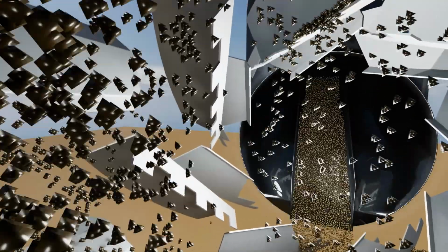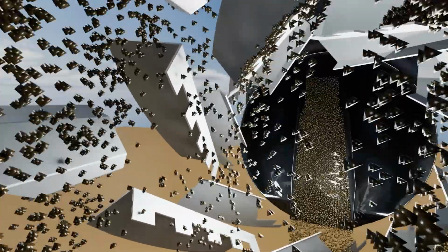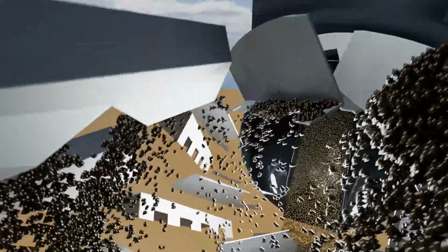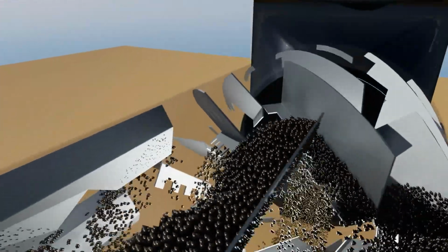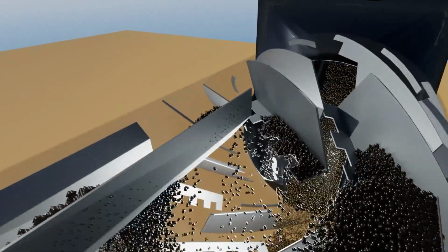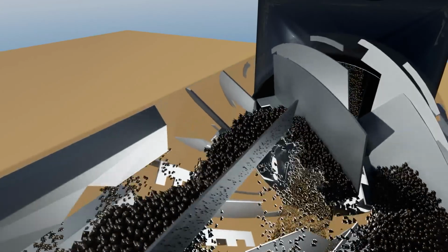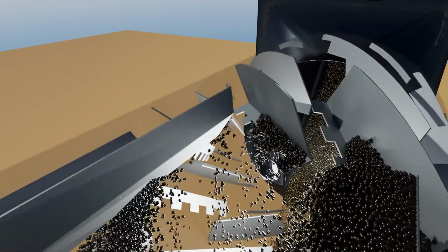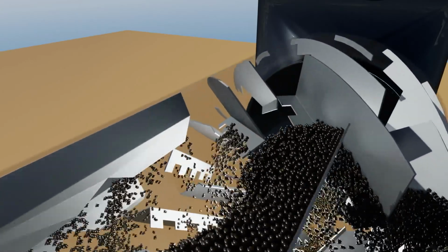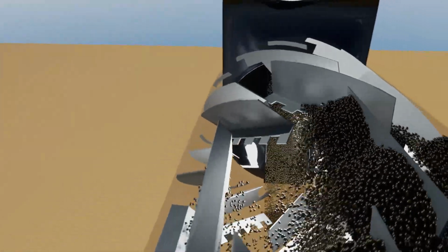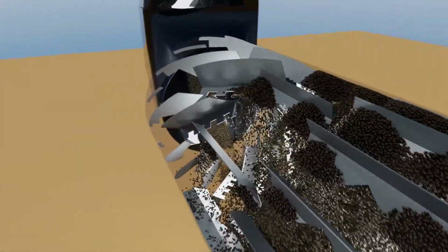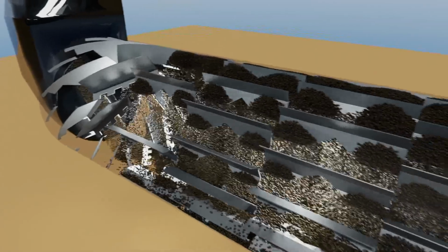Aggregate enters the drum through a gravity chute. The conditioning flights at the inlet end break up any clumps or sticky material. Showering or veiling flights lift and pour the material evenly through the drum where hot gas streams transfer heat to the cooler, moist aggregates.